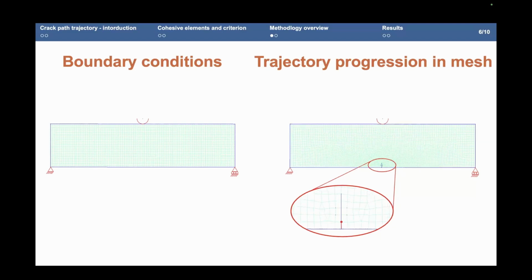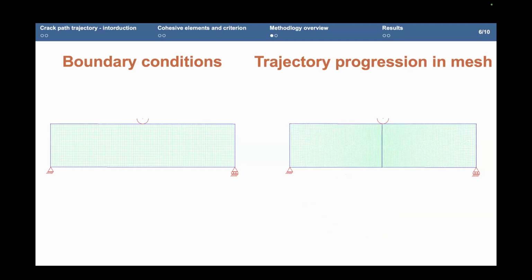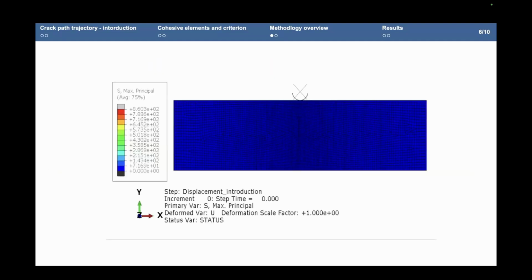And so for the next simulation, as you saw from the previous slide, the purple node is the next crack tip, and the one from before is actually an open surface in this simulation. In the next one, it will be 2 open surfaces and so on and so forth until we get the full crack response. On this trajectory now, we implement all cohesive elements again to get the force displacement curve.